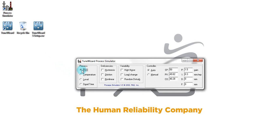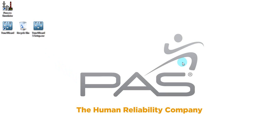The Process Simulator allows simulation of different types of loops and can be used in place of a real process. For the purposes of this exercise, let us choose a flow loop and let us place the controller in manual mode. The TuneWizard icon is used to start the control loop tuning program.